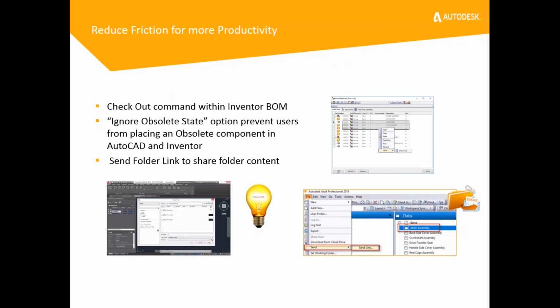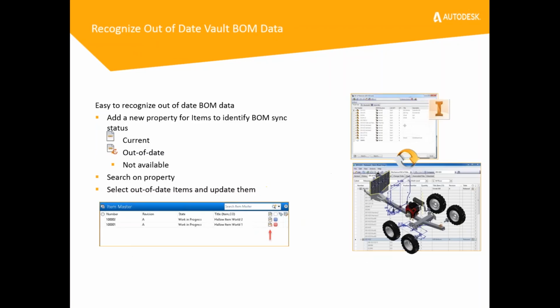All right, so another, if you're using the bill of material section of Vault, and I would say maybe 50% of our customers use the BOM section. A lot of them have other systems that they use. Maybe the designers aren't necessarily updating the BOM and getting it filled out before it goes into the ERP system. It just depends on the company, but if you have a long drawn out process for that right now, or maybe it's a separate application, I would consider utilizing, or at least checking out, the BOM capabilities within Vault. The nice thing about that is, you convert your entire CAD structure into a bill of materials, and then you can manipulate it right within Vault. And then from there, you can send it out, export it to your ERP system.